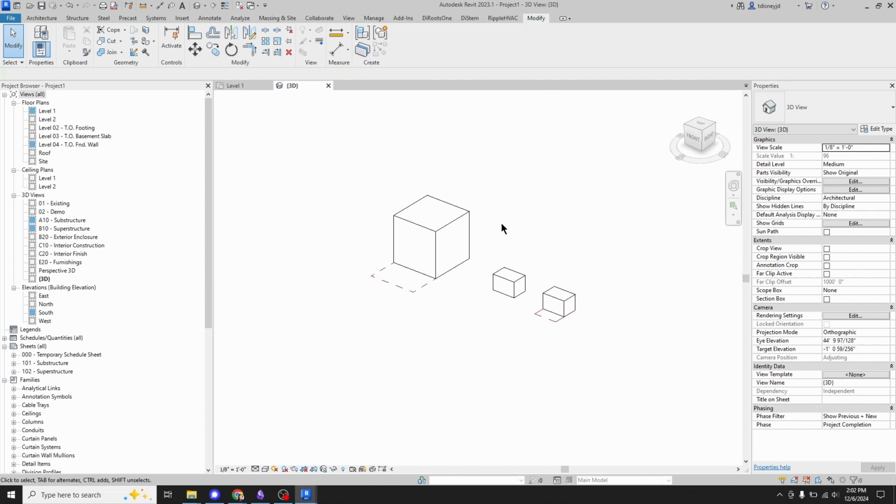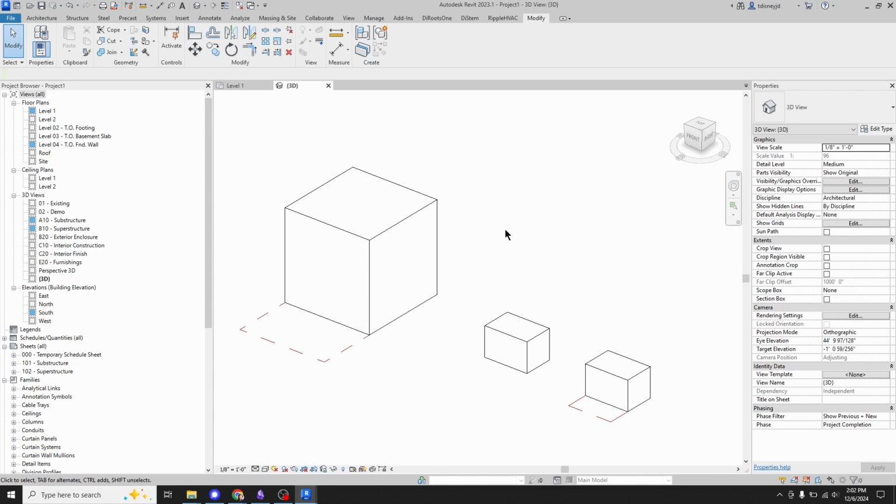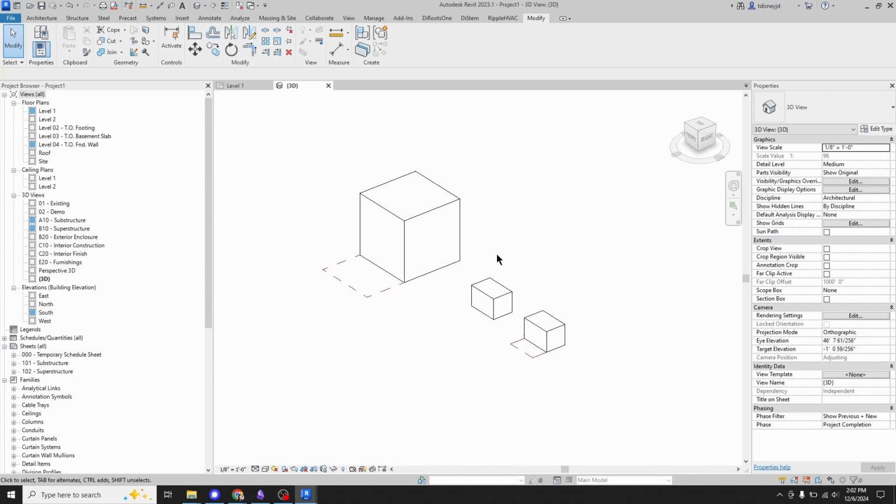And you can do a lot with just a box. Almost everything is just a box. Even tanks are basically boxes with a little margin of error. And honestly, if you don't have more sophisticated families on hand, you can do most of your design with just a bunch of magic boxes. Magic box AHU, magic box RTU, and you can just know where the duct connections come in and out, and you can bring them up there. And unless you're on the hook for LOD 300 plus designs where everything needs to be within an inch, that's good enough for almost most drawings.